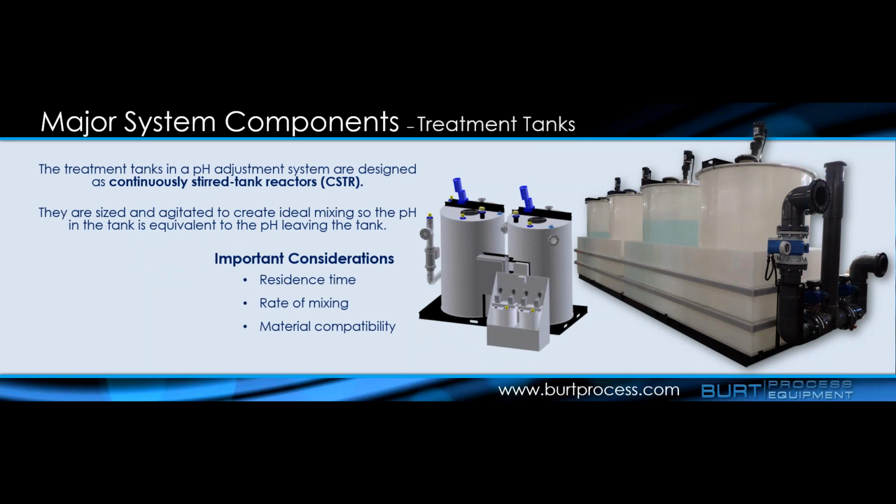And again, regardless if it's a flow-through or a batch, there are certain commonalities. The treatment tank is designed with what's referred to as a CSTR, a continuously stirred tank reactor. In chemical engineering terms, what that means is this tank is agitated as either the volume is held in a batch style system or as flow is allowed to enter it in a flow through system. And you are mixing this into a well-mixed solution. So the pH and the chemical consistency of this tank is uniform throughout.